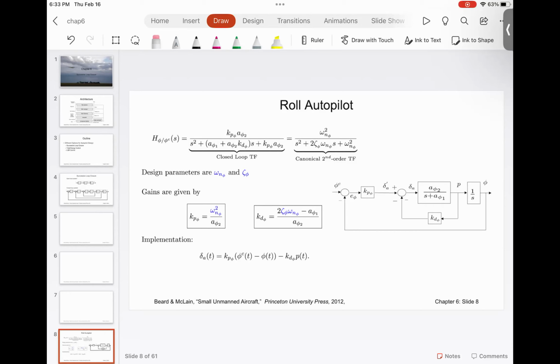Now here comes the next important question. We talk about tuning the spring, we talk about adjusting the damper. How is it done practically? If you have a damper and you physically want to change its damping properties, you can replace the damping fluid.